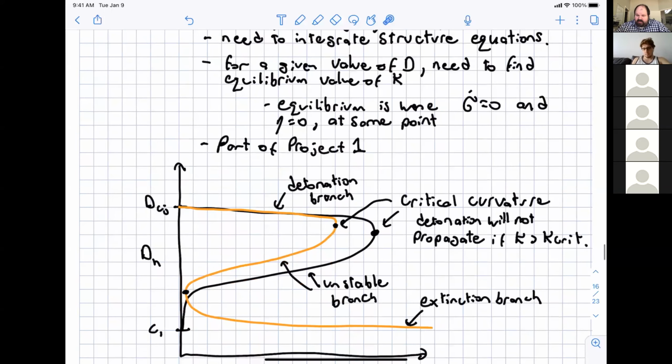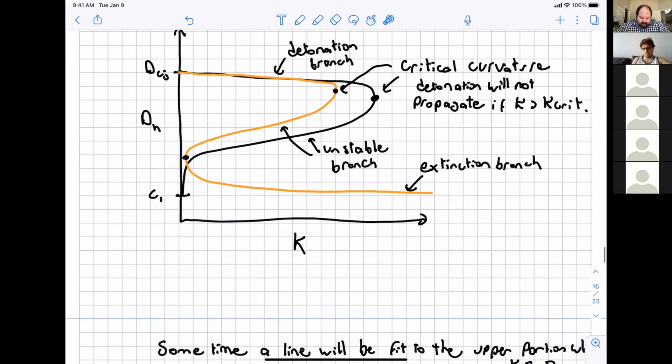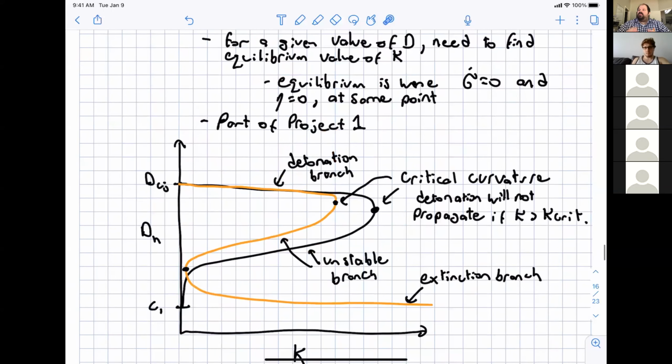But after you, there's a very nice algorithm that you can use for doing that. It's based on bisection and it's robust as hell. If it fails, it isn't due to the bisection method going crazy. It's just due to the ODE solver basically going nuts.